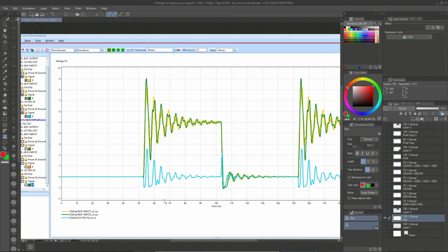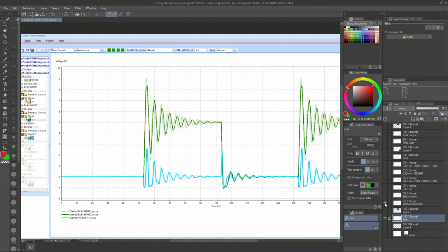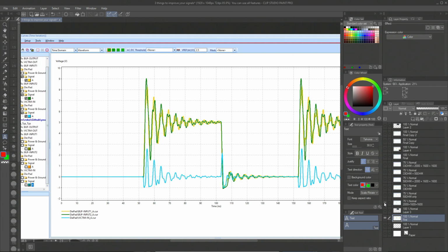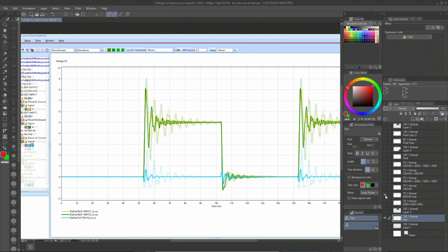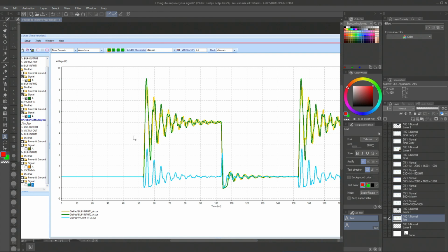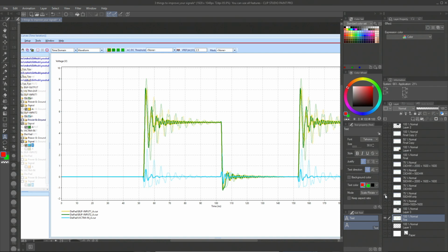This is the original bad signal, and if we would only adjust the length of the branches, this is what would change. Okay, in the background you can see the original signal. So this is the difference. If you would only change the PCB, this is what would happen. Okay, so from this signal, if you change only the PCB stack up, this is what would happen.